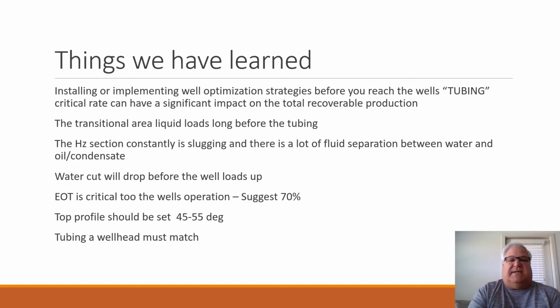One of the big things is that total production time in a horizontal well, which is quite different than a vertical well, does not necessarily mean better production. So we see a lot of horizontal wells where we'll switch them from 16 or 18 hours a day of production time to say 12 hours on, 12 hours off using a free cycle plunger, for example, where we have 15 or 20 minutes of off time and 15 or 20 minutes of flow time, and the overall production will come up 20 or 30% over, say, a conventional plunger that's only cycling 2 or 3 times a day with an hour off.